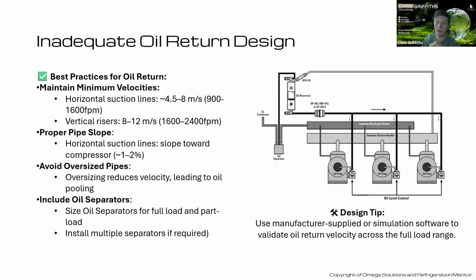A larger pipe will generally need to be a thicker gauge pipe work as well, because as it expands, you have more pressure forcing out the walls. And anyone who's looked at a pressure table for pipe work will notice as the pipe gets bigger, the maximum working pressure at the same gauge is lower. So you also need to consider that, making sure the pipe work is suitable for that scenario, even if it is oversized.